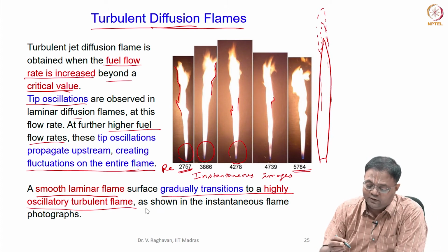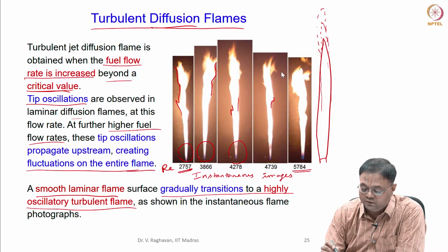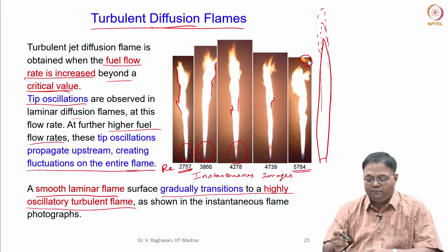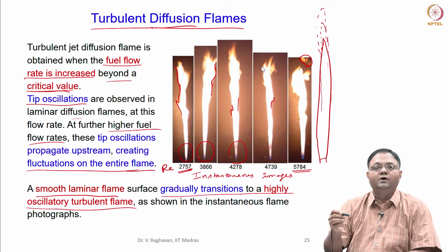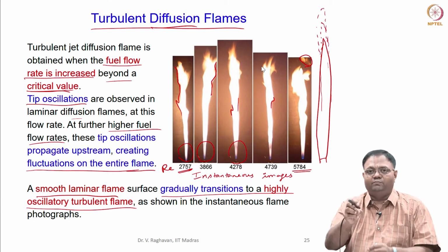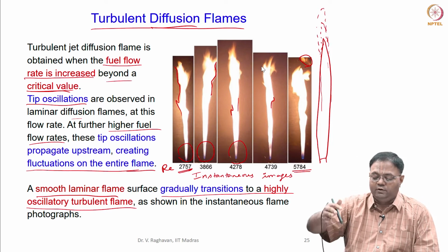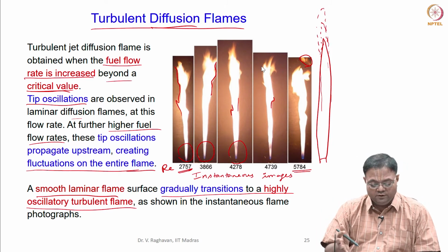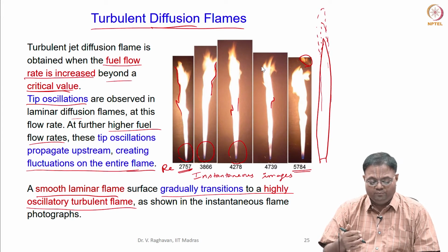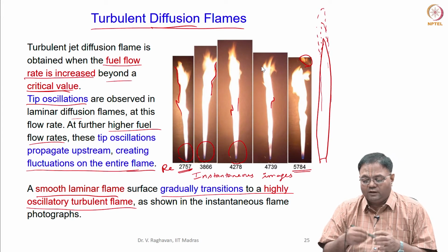And also we can see that there will be some puffing. You can see here some flame has just left. So, there will be some puffing, and due to the vortex shedding type of phenomena, the flame can puff and go off and again it burns. So, this type of vigorous oscillations are seen in the flame zones. So, other characteristics you will see.